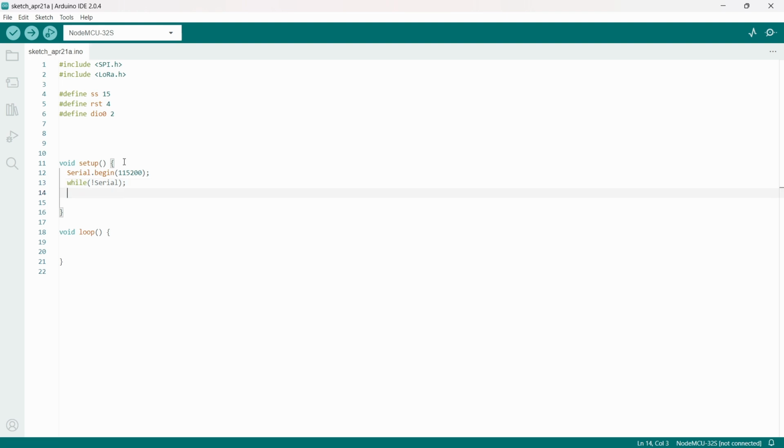Next, we are going to print that we are going to receive with this LoRa, right? So we are going to use this as a LoRa receiver. When you compare with STM32, programming for ESP will be very much easier. For UART communication, we have to create lots of functions for STM32. But when it comes to the ESP32, we just give Serial.print. So this will send my data over UART communication so that I can see it in the serial monitor. So this is a LoRa receiver, right? Receiver. Okay.